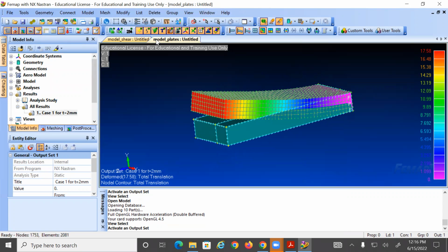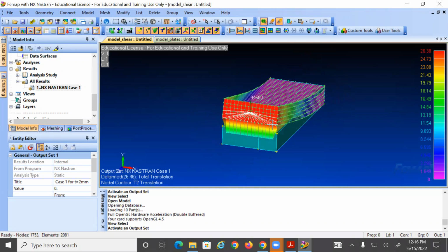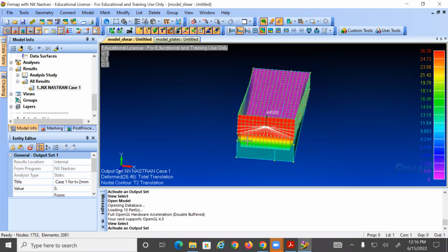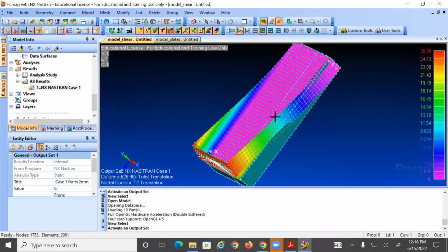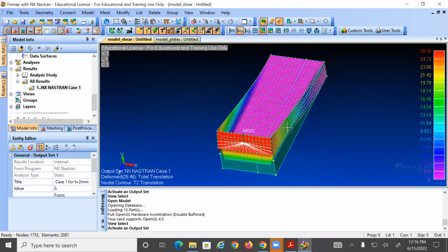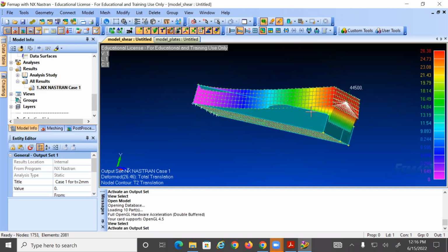If you want to go and check the shear values, you could go to this model shear and look at the values on the panels. Okay. If you look over here, when you put deform, you see what's happening, no? Some of these are not staying attached. Only the panels. So that makes sense because when we say this one, conceptually, what do we say?